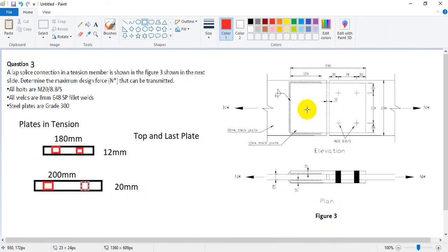I'm extracting all the information for all the analysis, not just for tension plate and tension. For tension plate, you just need the plate thickness and the section, and that's it. And you have to get the KT, as you can see here. It's almost symmetric, our steel connection, so the KT is going to be equal to 1, and we're gonna check that later, but this is obviously going to be 1. We have already discussed that. However, I'm gonna check it also.